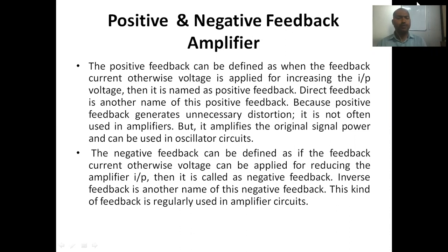Positive feedback generates unnecessary distortion. This is the reason we do not use positive feedback in case of your amplifier. When we use positive feedback in an amplifier, it generates unnecessary distortion. Distortion indicates that an unwanted signal is added with it, so noise is added, and the performance of the circuit changes.